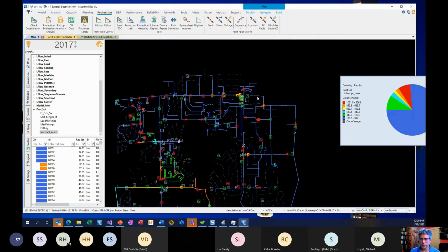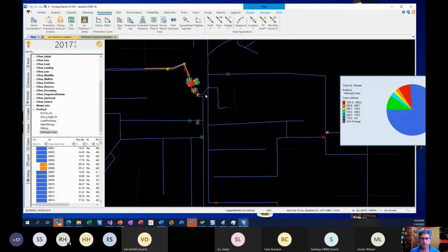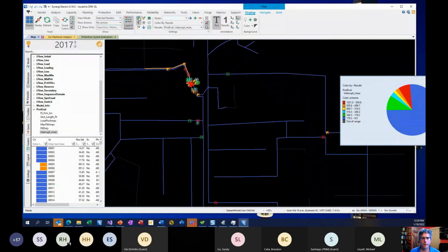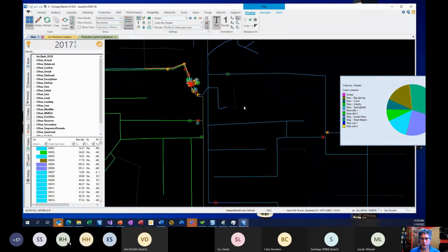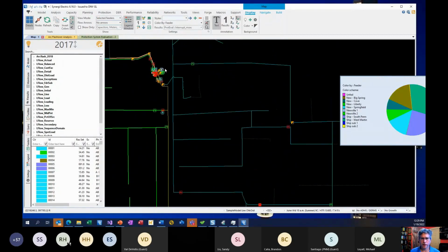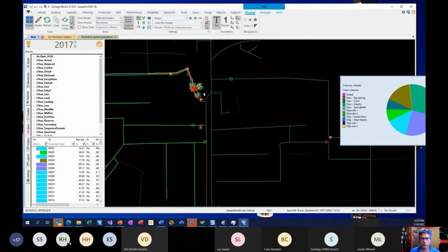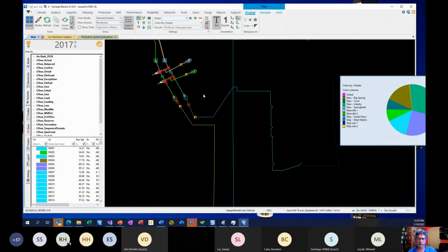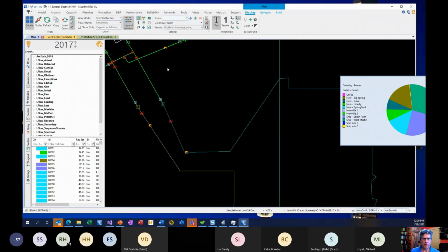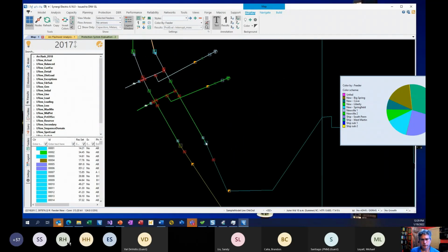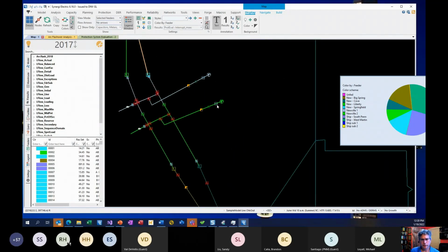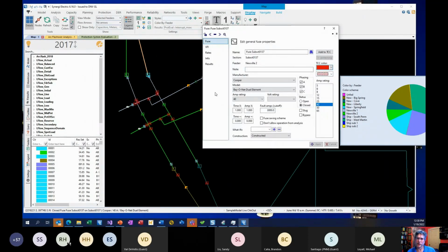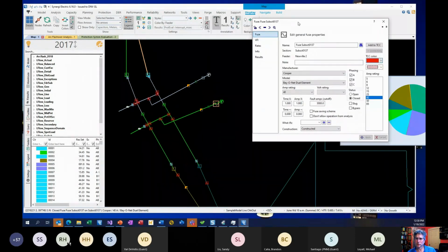In our case, that new cove feeder is up here. New cove is this little feeder right here. And our protection in this sample model is really bad. There's a bayonet fuse sitting up here outside the substation on this transformer right here that seems to interrupt just about everything on this feeder, which isn't good. So a lot of unhappy customers.